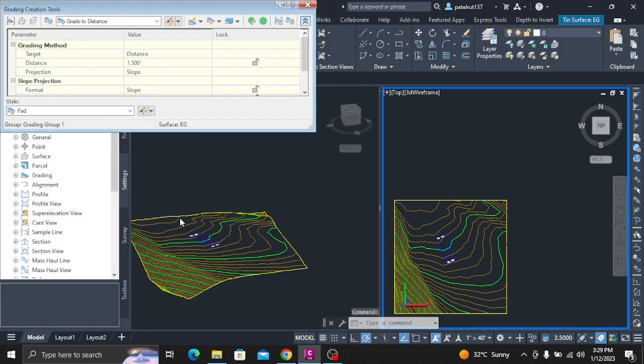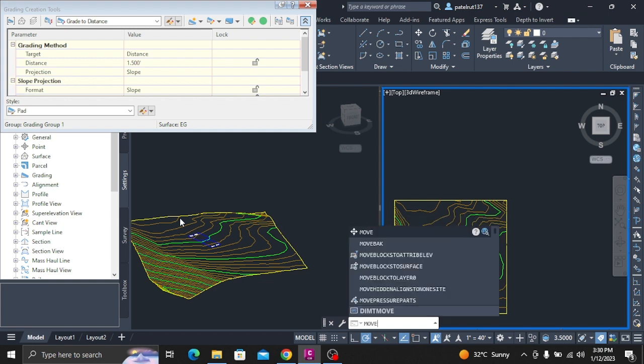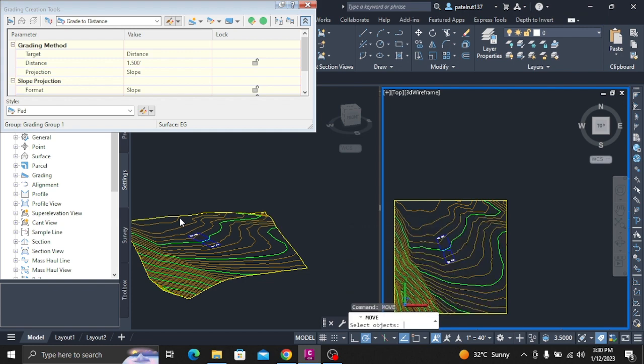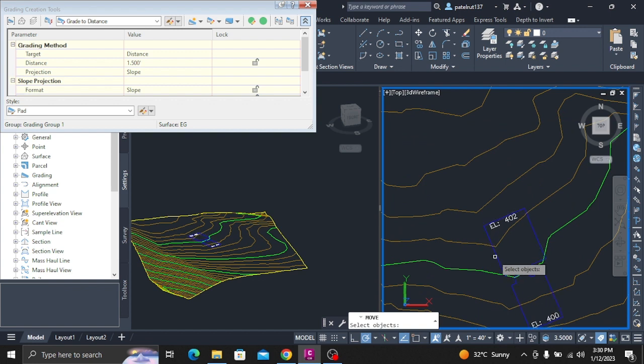In the right viewport, select Feature Line ABC. Right-click. Click Elevation Editor. The Grading Elevation Editor displays a list of the points of intersection, PIs, or horizontal geometry points, and elevation change points, vertical geometry points, along the feature line.